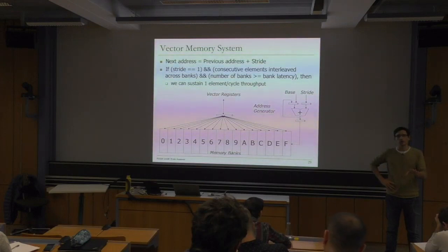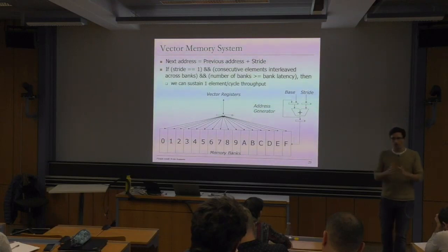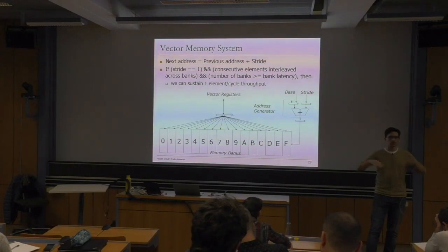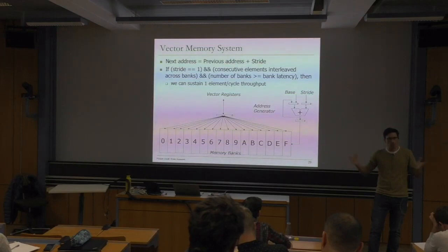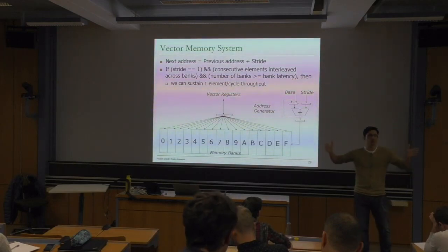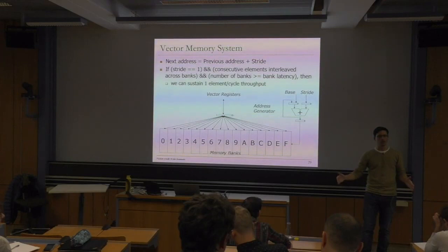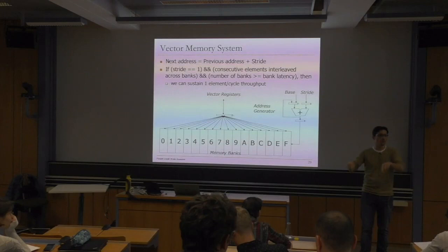It will depend on the specific architecture. For example, if you are thinking about an array processor where you have, let's say, 16 processing elements and each of them can execute every instruction like addition, multiplication and so on. You compute something using additions, and right after that the next instruction is a load, right? So in this case it could make sense to say, okay, if I have 16 processing elements, let's have 16 banks as well, so that we can issue the request for all of them at the same time.